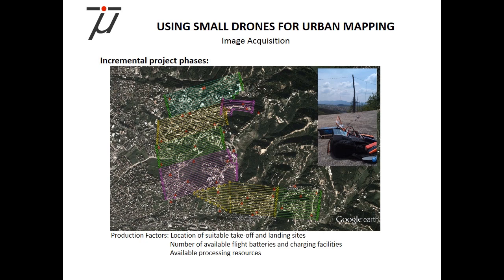But is each flight line just one mission? No, this is to give you scale. This is about 1.2 kilometers. So each flight covers 2 of these lines. So what you try to do, when you are this limited and constrained, is always have an even number of flight lines in your flight plan, so that you don't fail. That's stuff you learn very quickly. You want to come back to where you start photographing.